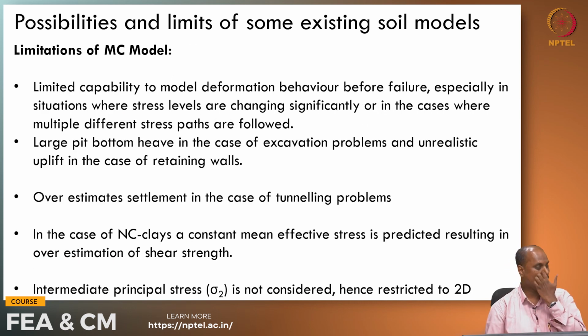As I said earlier, when it comes to the limitations of this Mohr-Coulomb model, the limited capability of the model to model the deformation behavior before failure is one of the serious limitations, especially in situations where stress levels are changing. Most frequently, if you encounter stress level changes, this model is not so good.